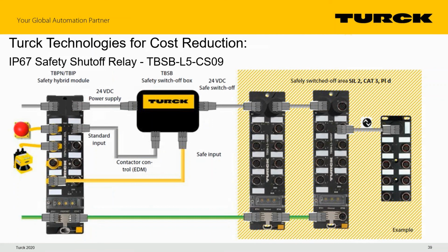Finally, we have our safety shutoff relay box. So one of the issues with the safety blocks is that the output is an OSSD output. So if you wanted to remove power from a bunch of blocks like this, you still needed to put a little box out there with some relays. So we have embedded those relays in a box. There's 2 relays in series with force-guided contacts that meet all the safety requirements.